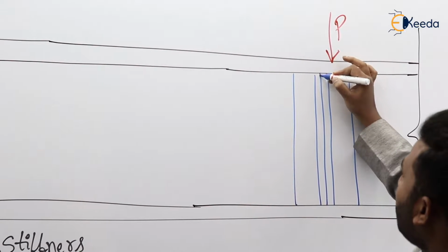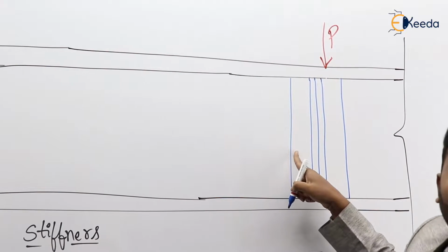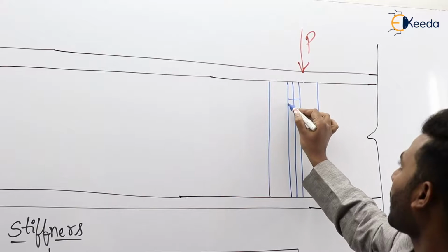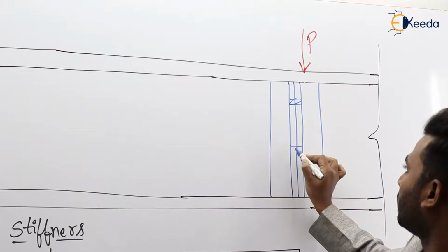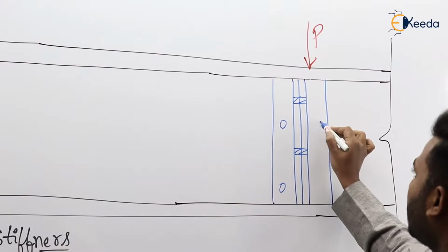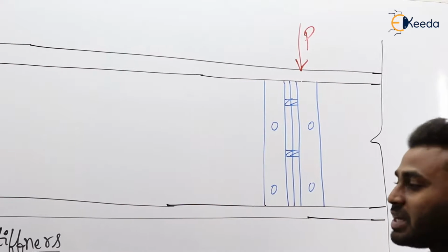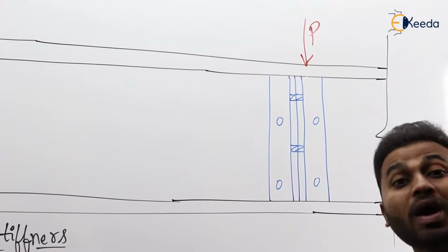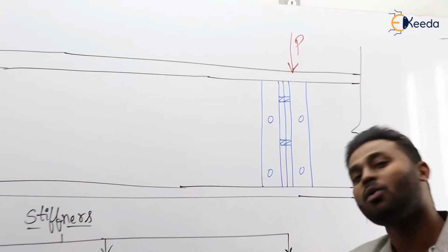Okay, these bearing stiffeners are provided exactly under the point load, so that is why they are called load bearing stiffeners. Now this is a location. Obviously, bearing stiffeners are provided either at the supports or at heavy concentrated loads. Now, what is its function?